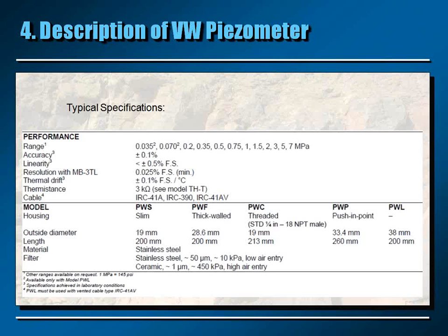This type of piezometer is also characterized by the fact that it needs to be vented, because it is important to note that our piezometers are absolute piezometers. They give an absolute reading of both the water pressure and the barometric pressure change. This is the case because the sensing element, the insert, is sealed. There's a vacuum in there.